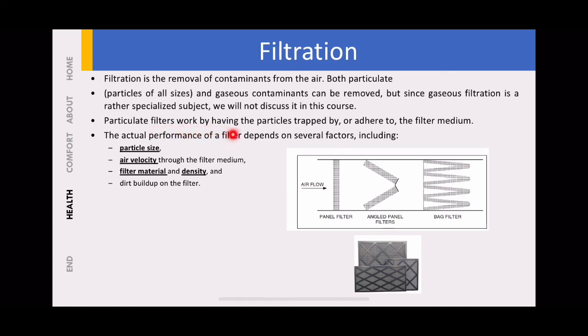Particulate filters work by having particles trapped by or adhere to a filter medium, maybe a HEPA filter or any kind of filter used to trap contaminants. The actual performance of a filter depends on several factors, including particle size and air velocity through the filter medium. The faster the better, but it must trap more contaminants. Then there is the filter material, what kind of material you use for the filter, and the dirt build-up on the filter, which sometimes needs to be washed chemically or just using water.